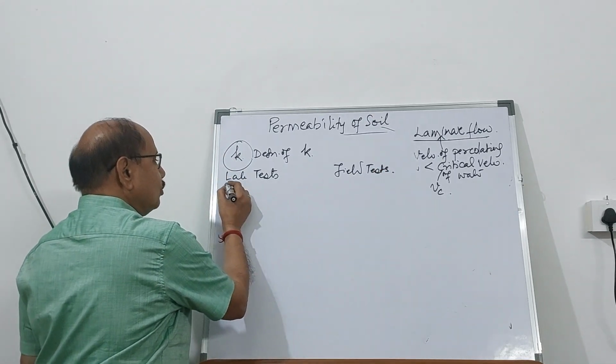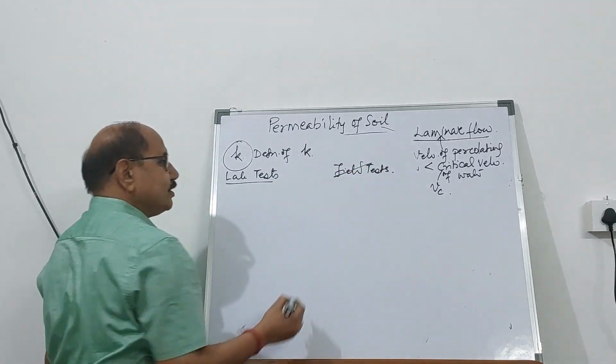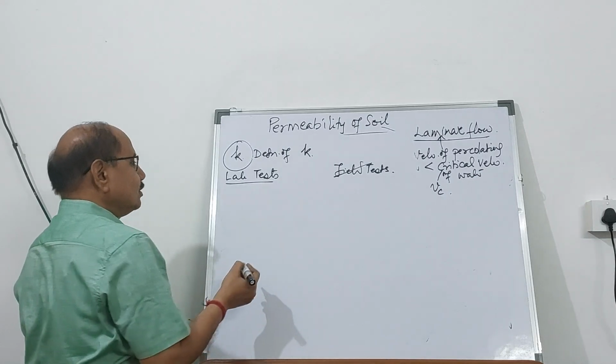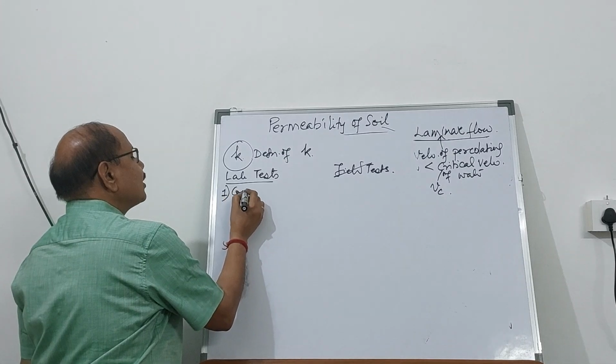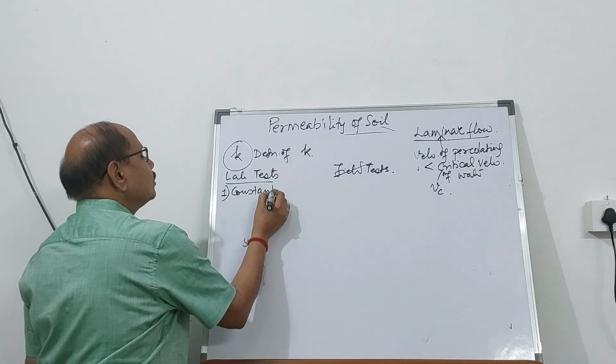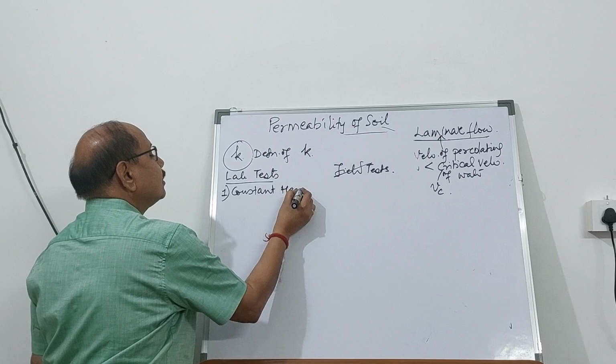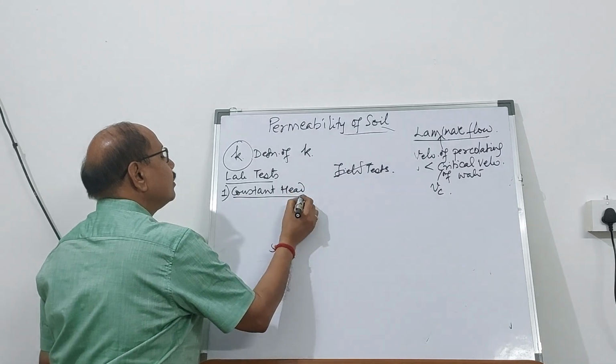So presently we will look to this field test later on we will discuss. In laboratory test, the famous test is constant head method.